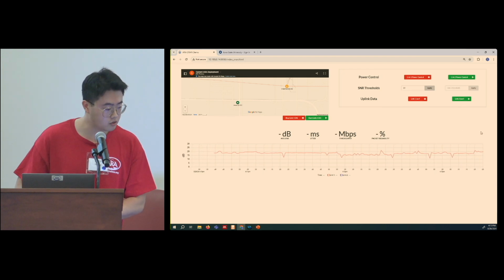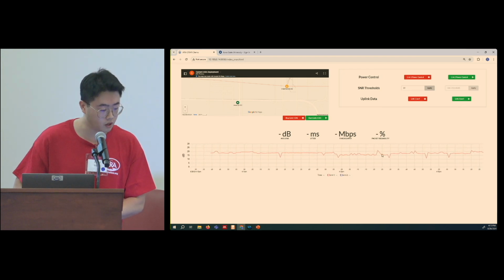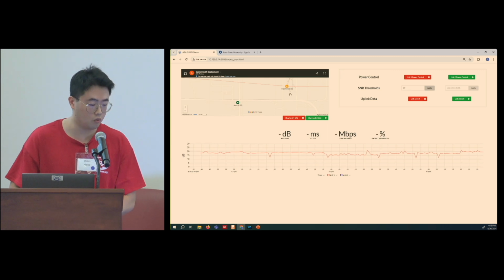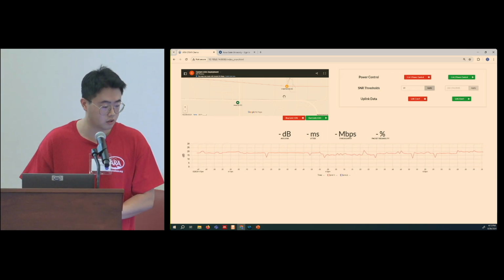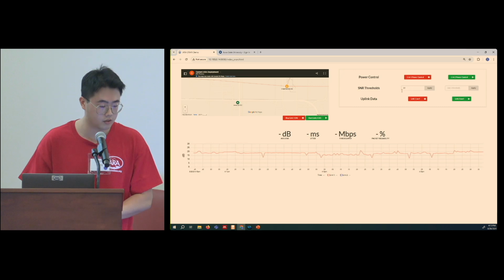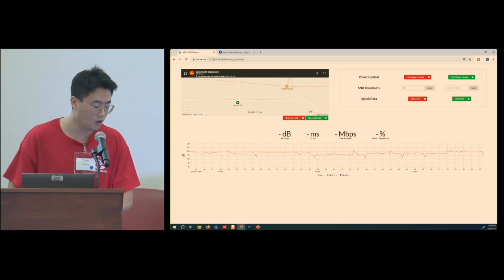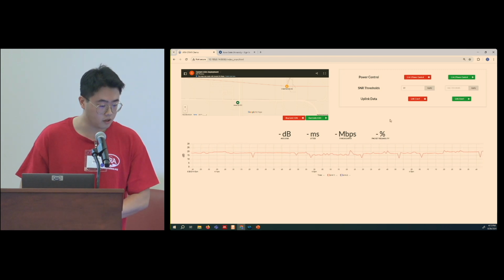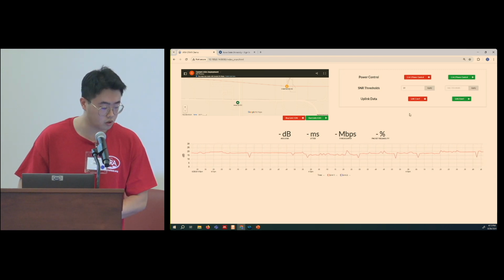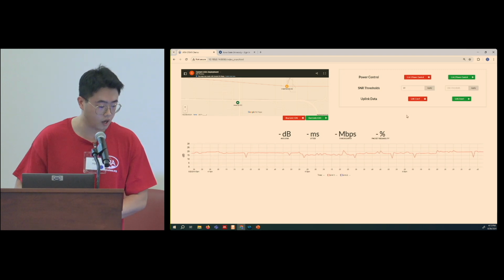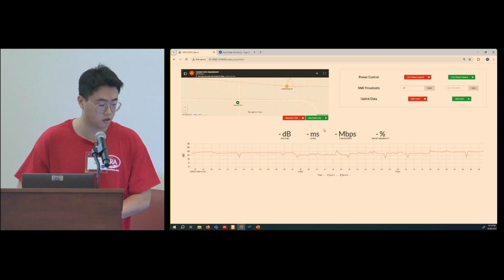Okay, we can see the SNR increase, and actually it can be handled above the 19 threshold. And for this link, when we do the test, I think the 19 SNR already achieved the maximum transmission power for this UE. And then I will stop it and show the impact of the SNR on some network metrics, such as the throughput, jitter, and the reliability.